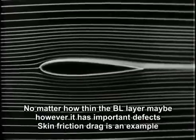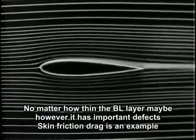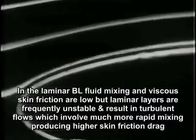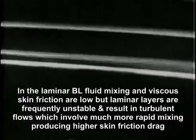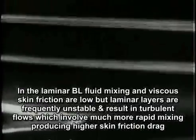No matter how thin the boundary layer may be, however, it has important effects. Skin friction drag is an example. In the laminar boundary layer, fluid mixing and viscous skin friction are low, but laminar layers are frequently unstable and result in turbulent flows, which involve much more rapid mixing, producing higher skin friction drag.